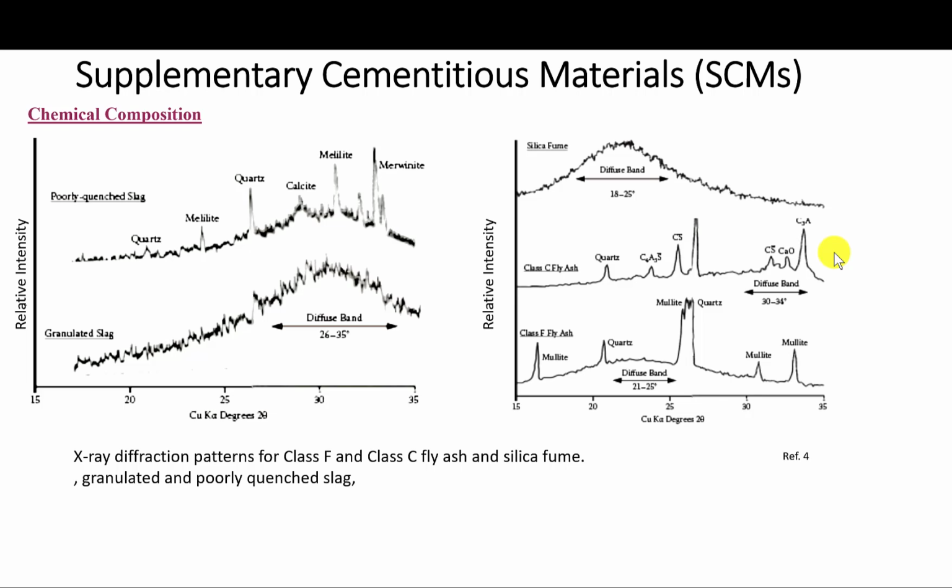But in general, cementitious class C fly ashes should not be used. I always did not specify them in my concrete. Basically, to avoid problems with the high water demand, early stiffening, or rapid setting because of the aluminate and the calcium oxide, the free lime content. Or in cases where we have issues with sulfate attack because of their alumina content, the C3A, as you can see here. So this one is to be used with care. I did not specify it.